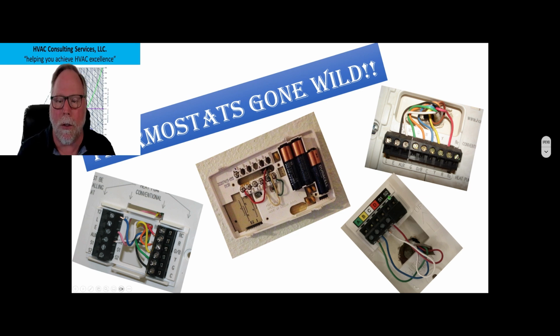Anytime you see an S1, S2, that is the outdoor temperature sensor hookup. The ABCD is a communication setup for a Carrier Bryant thermostat, Evolution or Infinity. Okay, now I know they've probably upgraded a lot since then, but there's a lot of those out there. Your Trane connection diagrams for communication are going to be different, along with your Honeywell communicating. So you really got to get into reading those instructions for those guys.